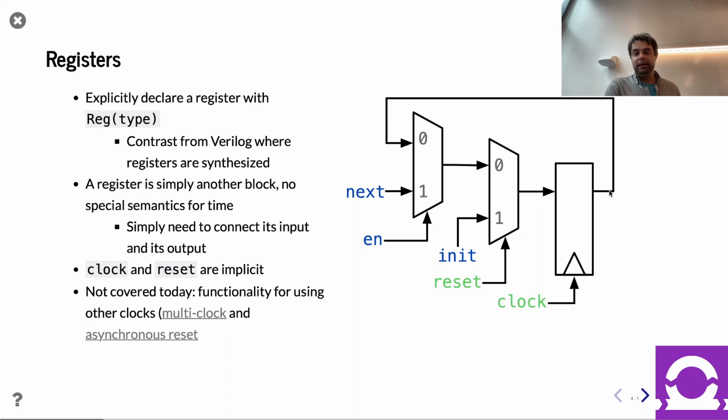Now, perhaps you want to have a register that has a particular initial value. Well, conceptually, this isn't necessarily the way it'd be done in the circuit, but you can imagine it's like having a mux. If reset is true, we take the initial value we want. Otherwise, we take whatever we're trying to load in. And maybe we want a flip-flop that's even more sophisticated, rather than just always writing a new value. We only write a new value if the enable is high, right? So in this case, we take a new value if enable is 1. Otherwise, we keep loading the same old value back in.